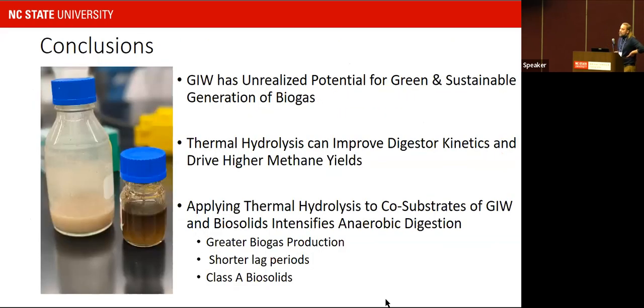During this presentation, I hope that I've made the case to you that grease interceptor waste has unrealized potential for green and sustainable generation of biogas and deserves further investigation, and that thermal hydrolysis has a role to play in that investigation and can drive higher methane yields and improved kinetics, especially when applied to co-digestion, in which it intensifies anaerobic digestion with process benefits like greater biogas production, shorter lag periods, and the possibility to generate Class A biosolids.